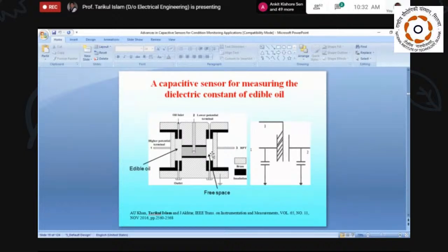Here we are trying to measure the dielectric constant of the liquid sample. The dielectric constant is basically the ratio of the capacitance with the oil to the capacitance of the air capacitor. This ratio, for symmetric operation, is going to nullify different effects because both have identical effects. So it is a reasonably precise method for measuring the quality of oil. You can even use this structure for measuring the moisture in transformer oil. But we have used this structure for measuring the dielectric constant of insulating oil.